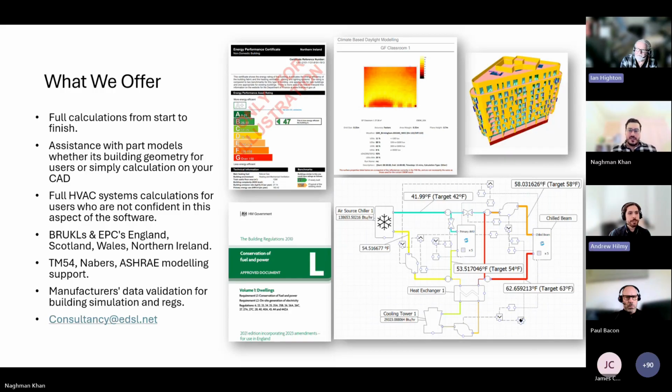It depends what you want to feed in. For example, we have had people feed metered data straight into a load component, and then they can attach that load component to the Waterside in order to model the effect of changing your Waterside on the actual data that went into the load components. That's quite easy to do. So basically, you remove the airside modeling and just put a load component in to represent the airside loads, and then you can just do the waterside effectively.